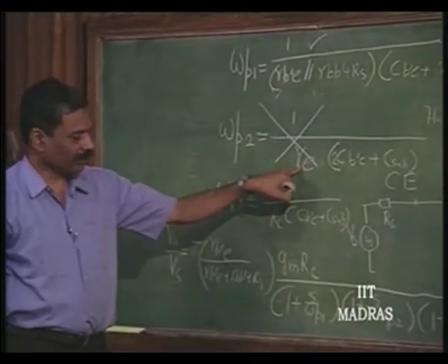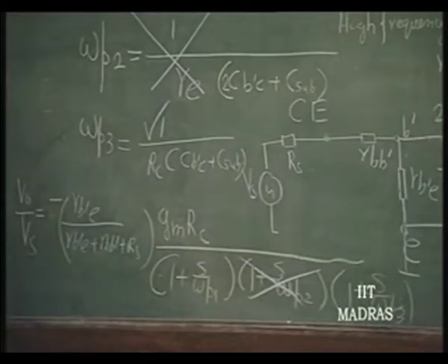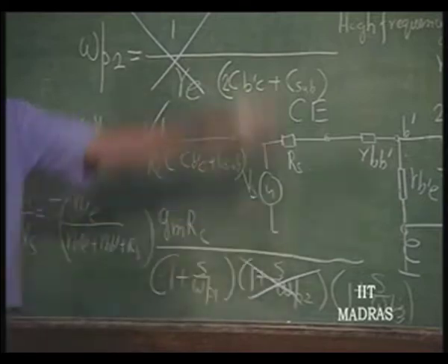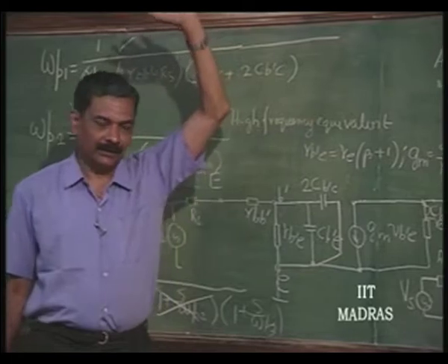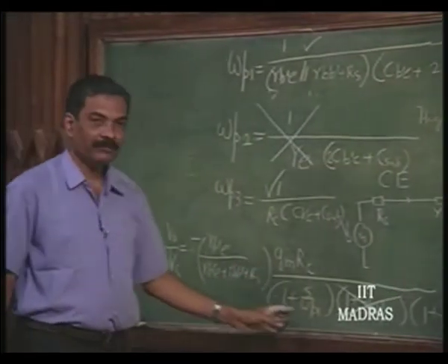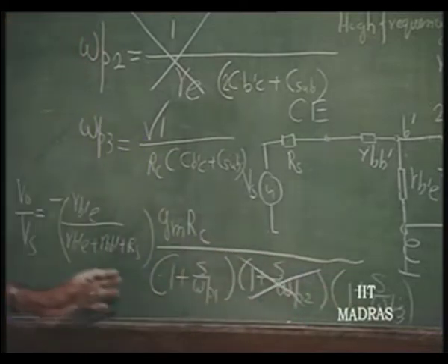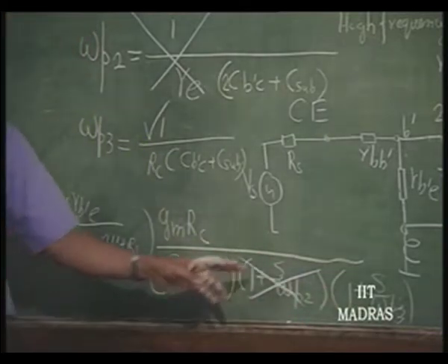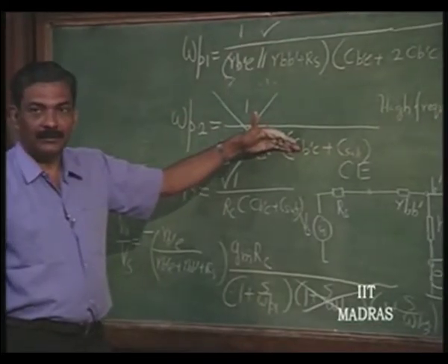So, almost nearly short circuit. So, this pole is of no consequence at all, right, and it is really speaking a 2-pole system even now, because this pole, intermediate pole, is at very high frequency, at which point the gain might have fallen off to less than 1. So, because of omega p 1 and omega p 3, the gain fall off occurs, right.